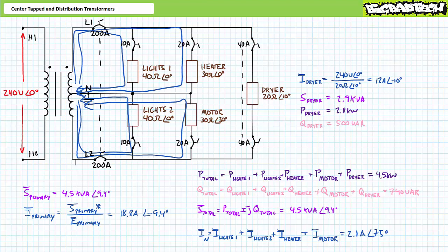You'll note the single-phase loads require the neutral line to function as intended. As these examples illustrated, any imbalance between L1 and L2 results in current traveling in the neutral line. Only in the very rare occasion with equal loads on the opposite phases does it result in no current traveling the neutral line. This is one of the compelling reasons circuit breakers make or break connection with the hot or high side of the distribution transformer rather than the neutral line.